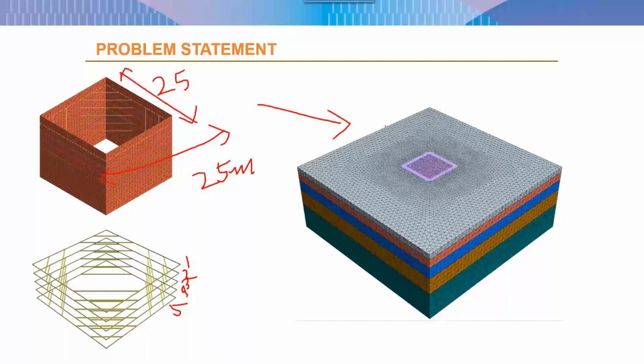So the whole point of making the model big is that there are two regions. First and foremost, your stresses and your plastic boundaries around the excavation should not reach the outer boundary, because it will give you wrong results in that case. Now, similarly, along with the lateral boundaries, the total boundary should also be deep enough.